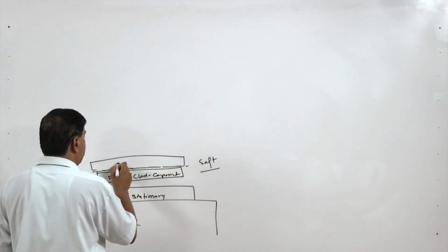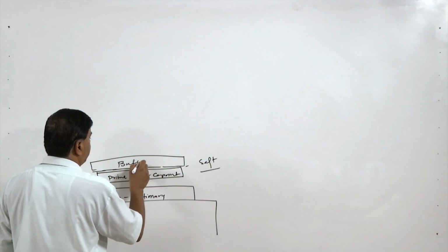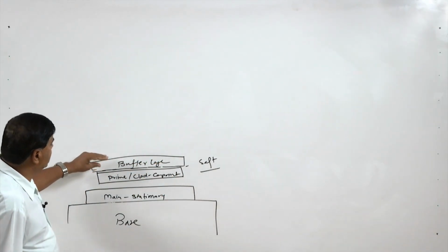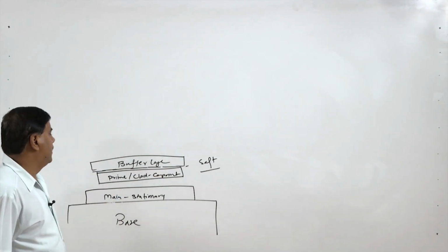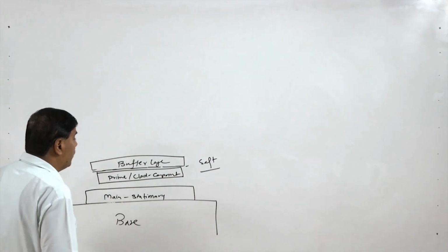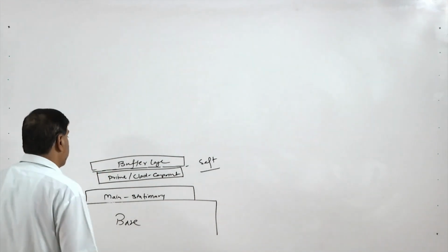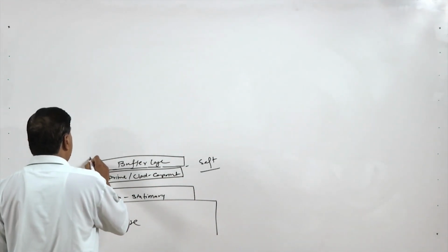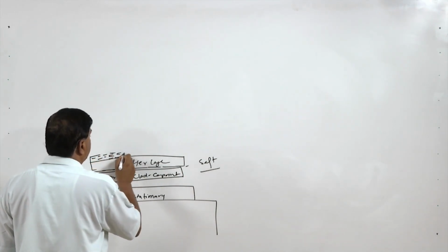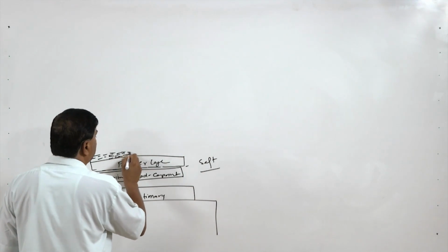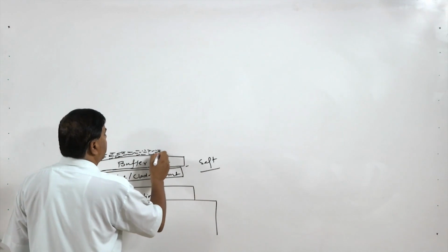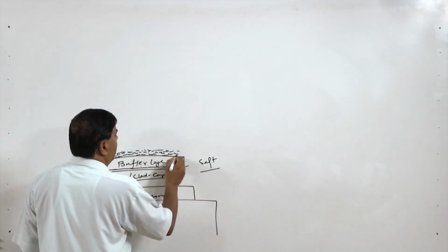The buffer layer protects the prime or clad component from damage due to erosion from the explosion, and over this we normally distribute the explosive, or sometimes it is placed directly over the surface of the prime component.